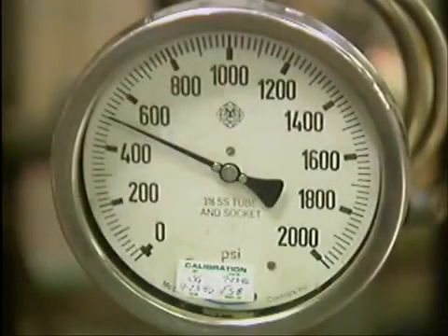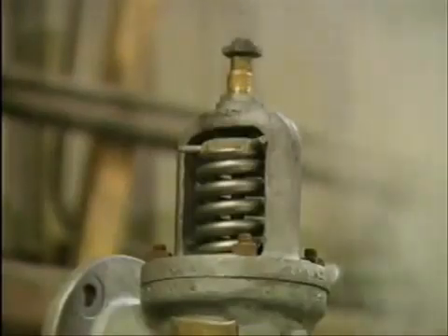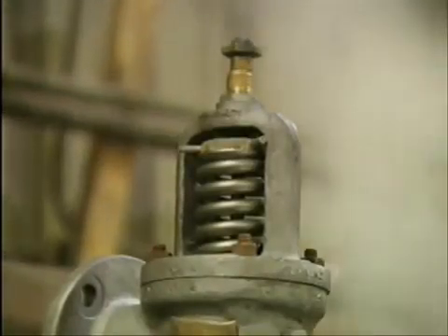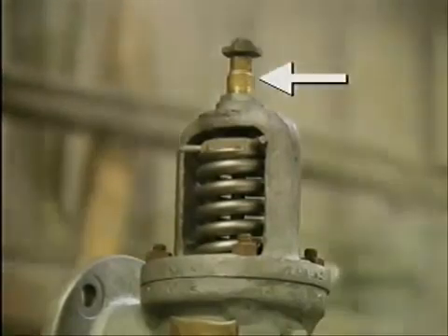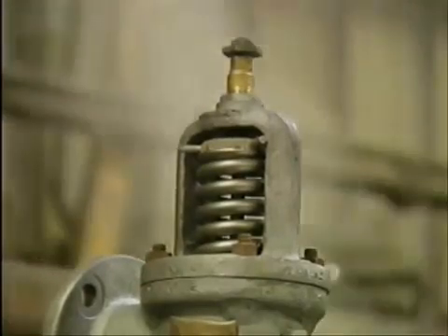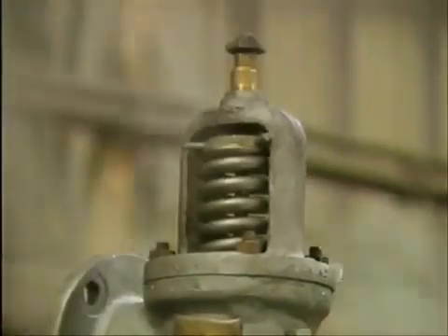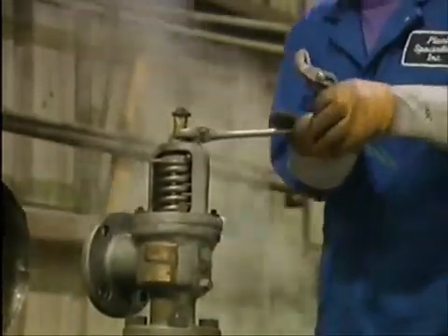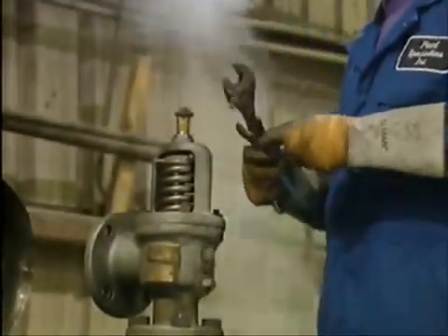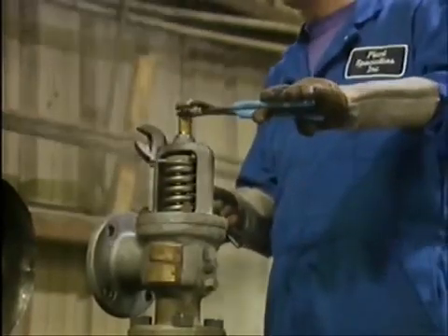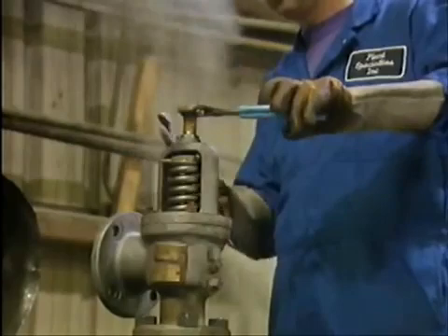The parts will then expand and contract at the same rate during the test. In any case, when you're testing popping pressure, you're checking whether the valve opens when it's supposed to. If it opens too soon or too late in relation to the valve's set point, you must make adjustments. For this huddling chamber safety valve, you make set point adjustments by turning the compression screw. But before you can do that, you must lower the pressure so that there's no chance of the valve opening accidentally while you're working on it. You must also break the lock nut free. If you try to turn the compression screw without loosening the lock nut, you'll probably damage the screw.